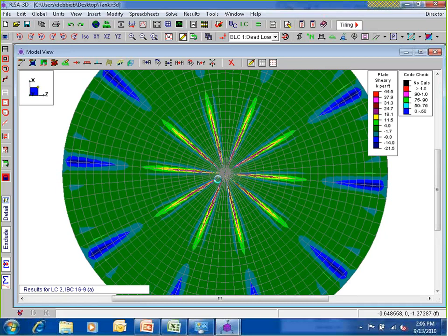And if we want to look even closer at these stresses, or exactly what's happening at a certain area, we can use a couple of our other tools. The first tool we might want to use here is something called our internal summation tool. If you click on that, it looks like a summation at the bottom left corner, and it will be available here when you have a solution present.